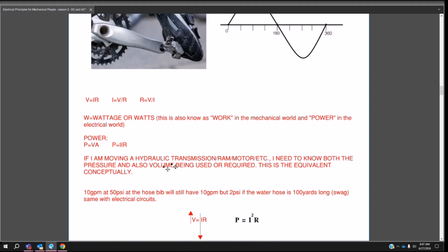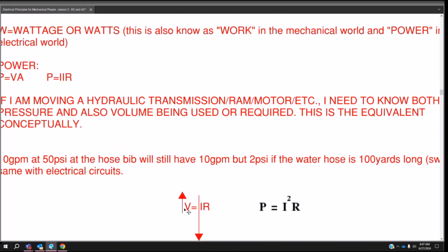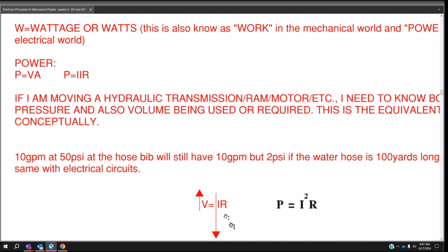As you can see in this concept, if I can increase voltage, I get a squared decrease in current because of the power loss equation. That's why I want a higher voltage, because I get less loss, I squared R loss, in my circuit.